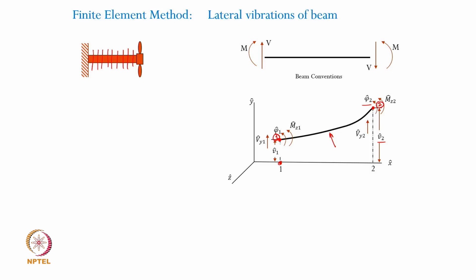There are corresponding shear forces and bending moments, as you are quite familiar, having discussed the transfer matrix or Myklestad-Prohl method. There is a slight difference here in terms of the assumed sign conventions, but that is how we define them. Like Vy1 and Vy2 are the shear forces at the two node points, and Mz1 and Mz2 cap are the nodal bending moments at the two respective nodes.